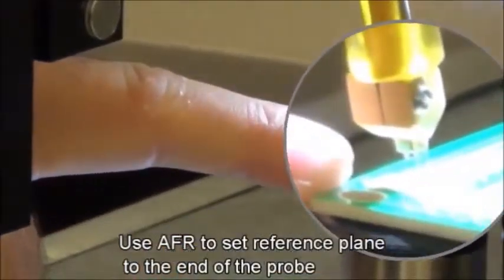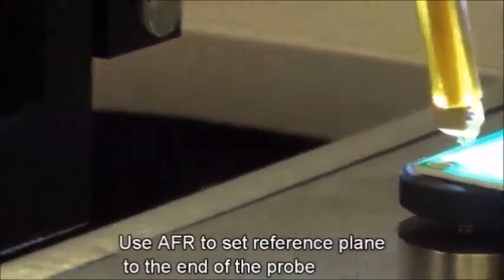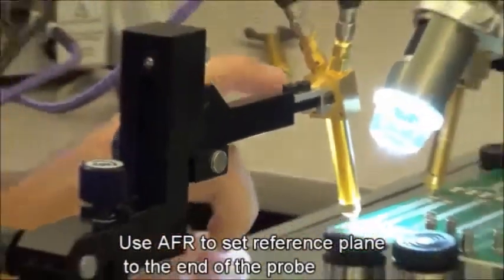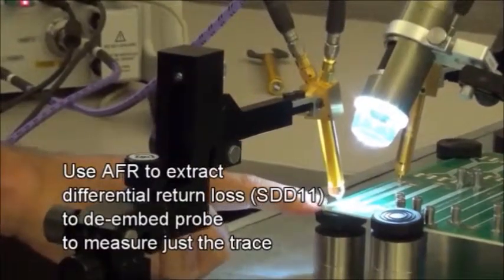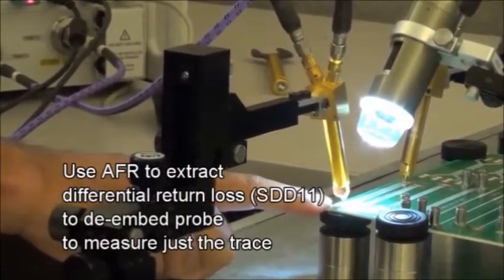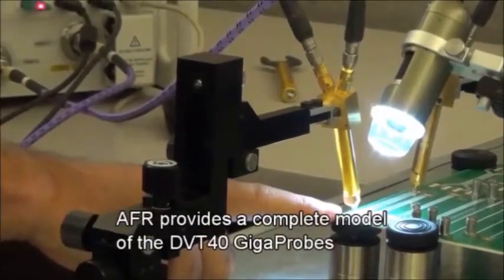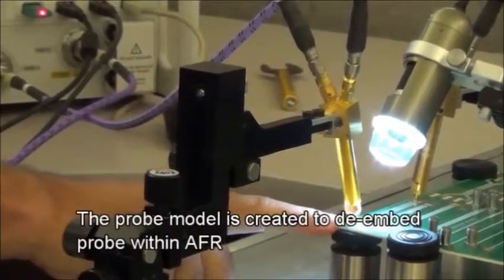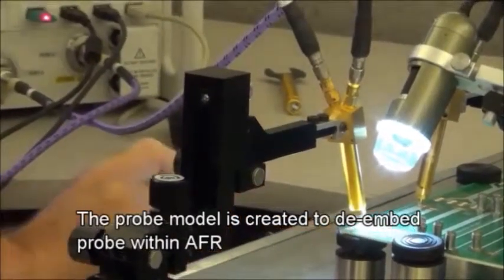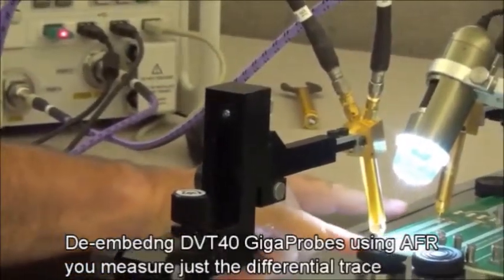And so here, we're going to actually use AFR. We're going to derive the S-parameter model of the probe by using an AFR SDD11 measurement. And with that one reflect measurement, we're able to get the complete model of this probe and then de-embed that inside AFR and get just the measurement of the trace. So let's show how that happens.